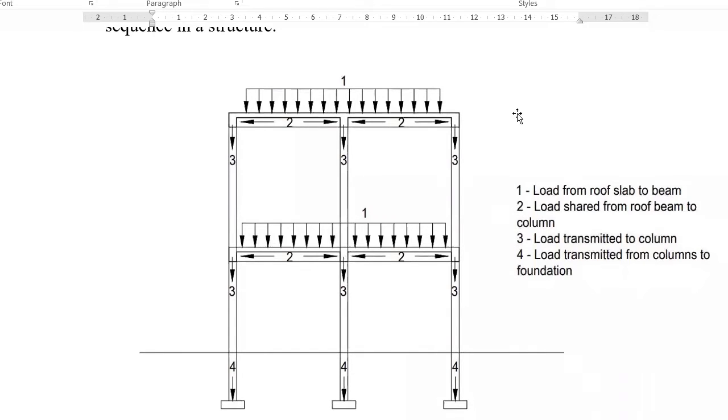You need to understand that the pressure obtained from the ratio of force over area should not exceed the one obtained from your geotechnical report for it to be true. If it exceeds, there's another means, but that's practically enough for this class.